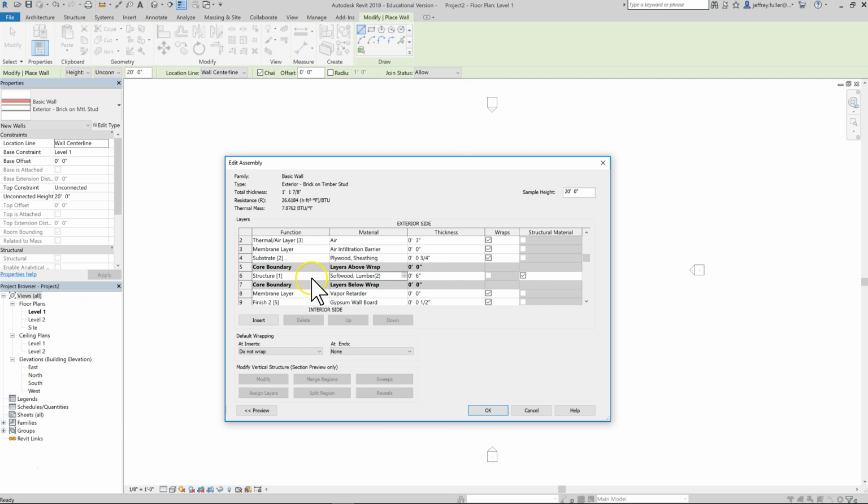All right, now the next thing I want to do is change my thickness, because the thickness that we're concerned with is how it's going to actually affect the width of the wall, the thickness of the wall itself. So it's going to be 3.5 inches, and I have double quotation marks there. I don't need that. All right, so it is structural material, 3.5 inches, and it is the highest priority material. That's what this 1 means right up next to structure. And that means that it will override any other priorities like priority 2, 3, or whatever when you start building your wall.